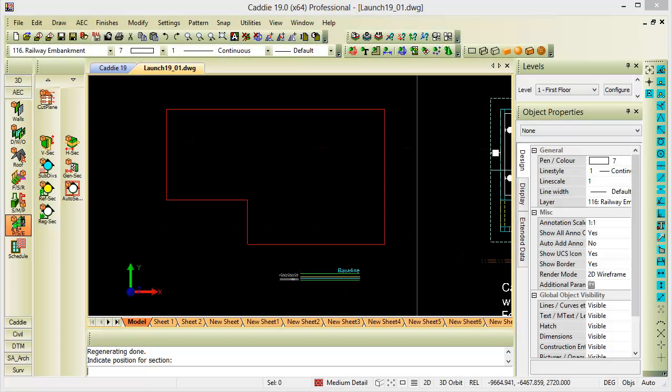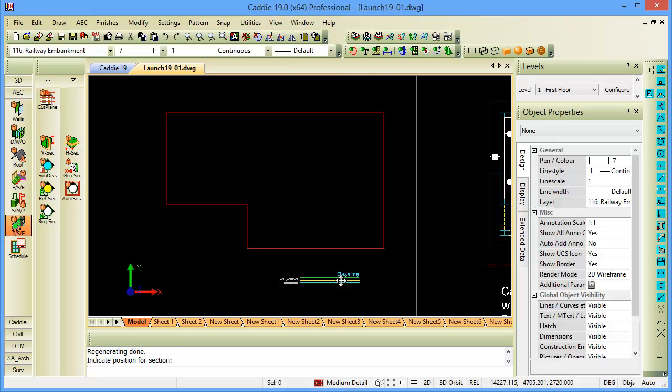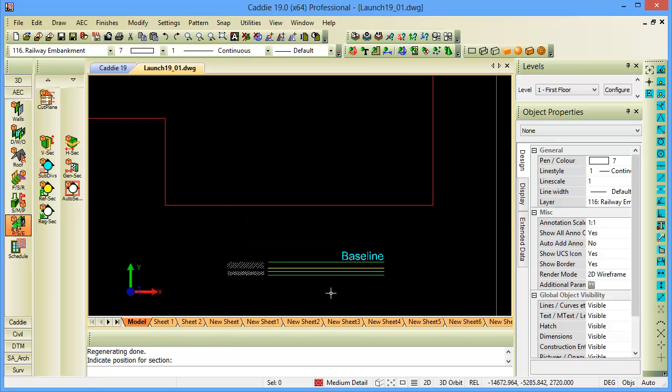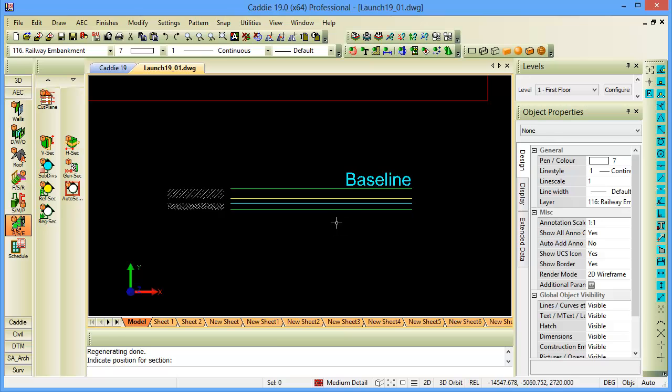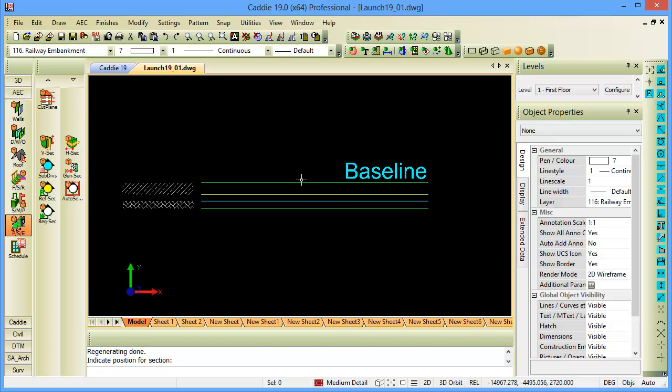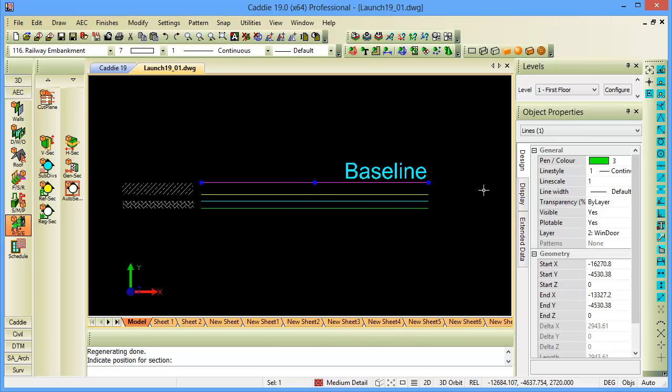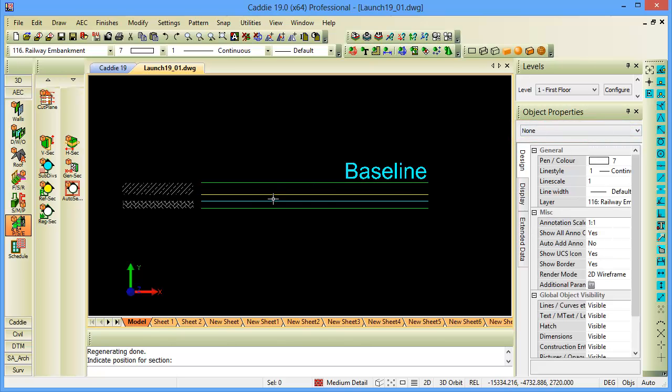In this exercise I'm going to show you how you can create an AEC wall style from basic lines and hatches that were drawn in your drawing, and that will be followed by how to easily create walls by applying it to polylines. First of all, in my example I've got a couple of lines drawn. It's just normal lines, as you can see in object properties.